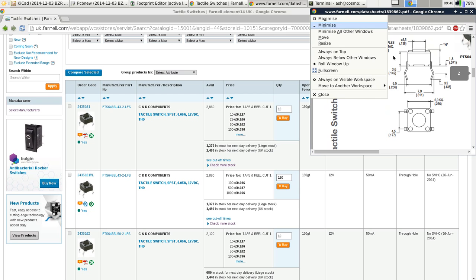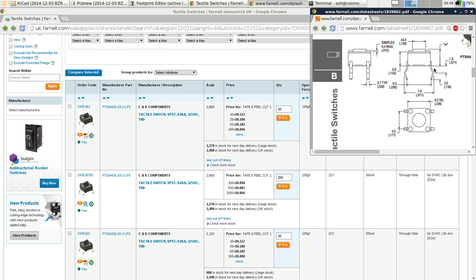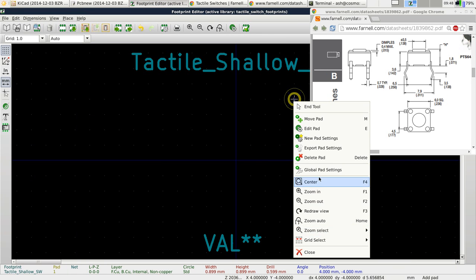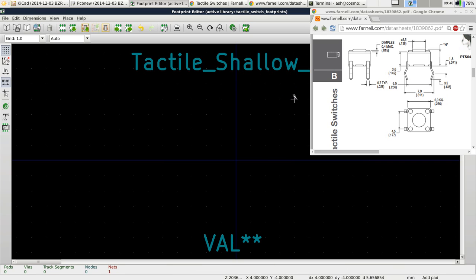Right, stay there this time. We need a 4.5 mil spacing there. So what I typically do in this case is I will set up a custom grid, because then I know I can get it perfectly aligned. And what I want to do is, we're going to have it so that the grid is 3 mil spacing in the x-axis, so that there'll be exactly 1 point there and 1 point there.